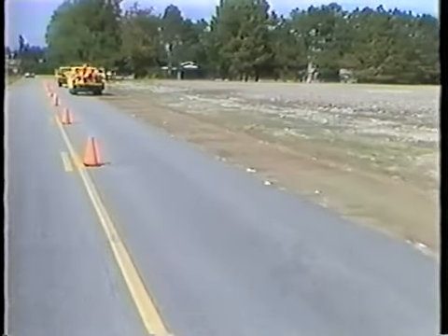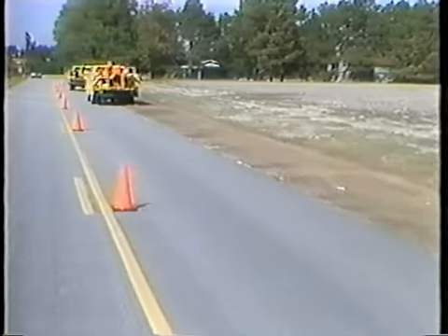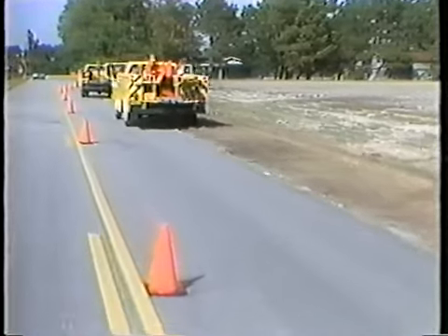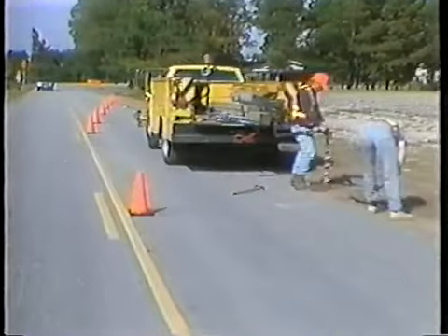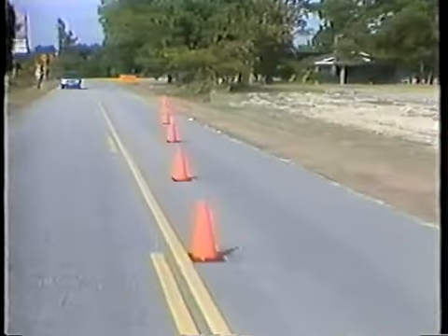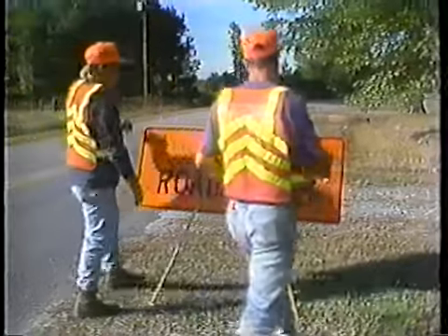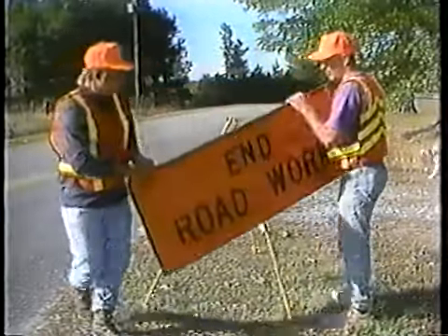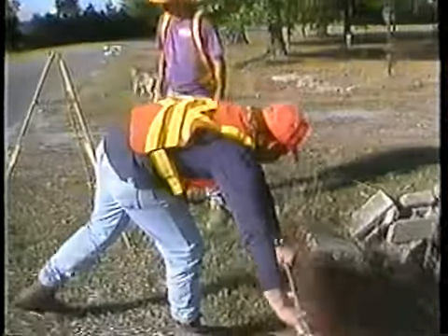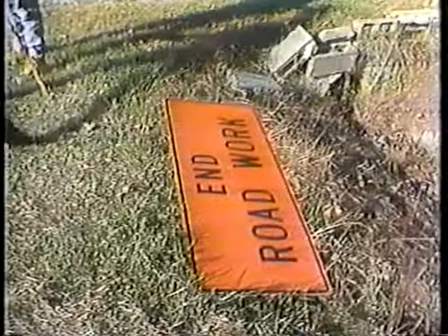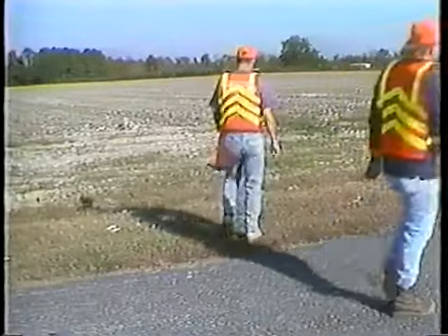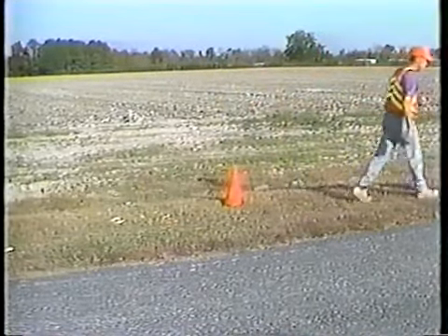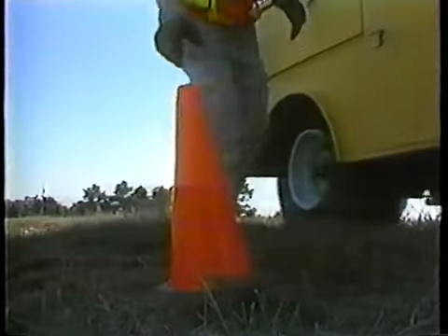As previously emphasized, the best way to evaluate traffic control is to drive through the work zone after all the devices are in place. Now, the work activity may begin. After the project is completed and all workers, materials, and equipment are off the roadway, the traffic control devices are removed in reverse order of installation. Remember, a good technique for removing the devices is to first place them on the shoulder of the roadway, then pick them up in the direction of traffic flow.